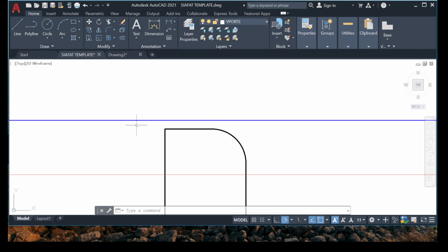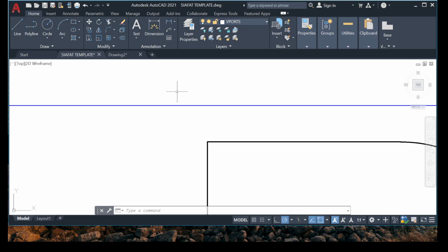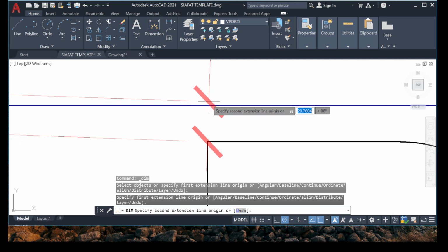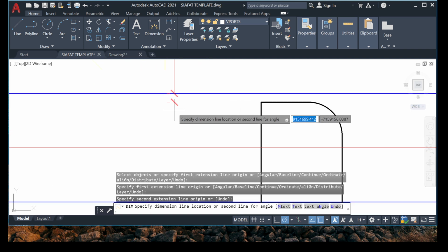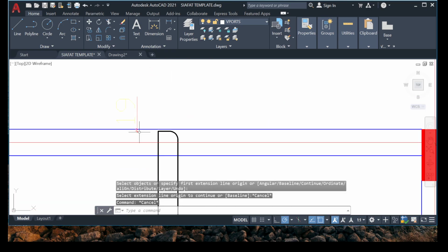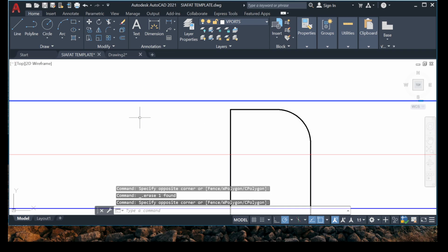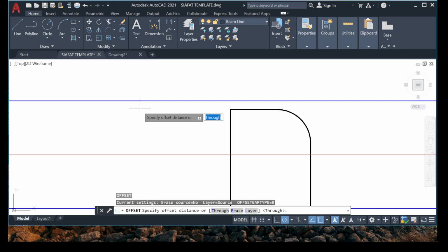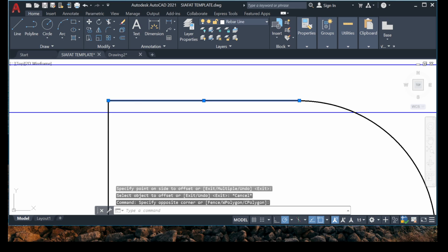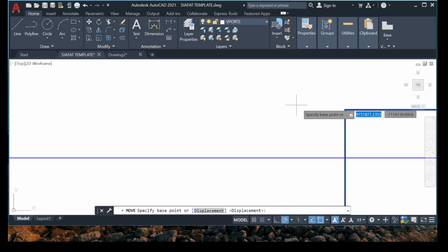So this one, the concrete cover should be 25 mm. Let's see what we have here. Providing, this one is 19 mm. So let's move this. Let us do it: 0, enter, 25, enter, all together. So let's move this to the cover. So let's bring this here.